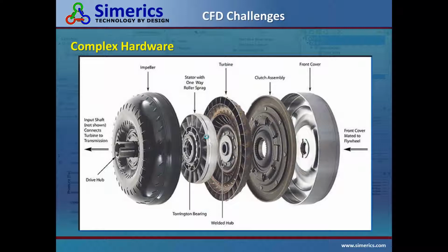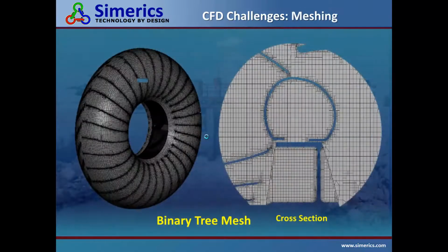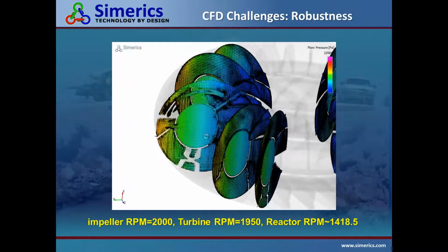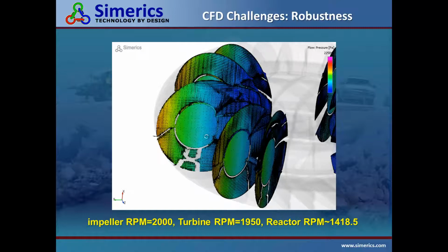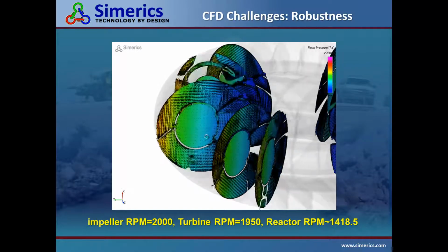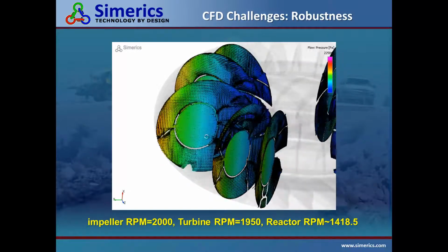CFD challenges. No method of testing is without challenges. In this case, the CFD challenges are as follows. Since the hardware is rather complex, the computational domain must be resolved using a mesh with adequate refinement of small-scale geometric features such as leakage gaps and balance holes, and must resolve regions of high flow field gradients such as boundary layers. The software must be robust enough to obtain converged solutions to problems which are inherently difficult to model.